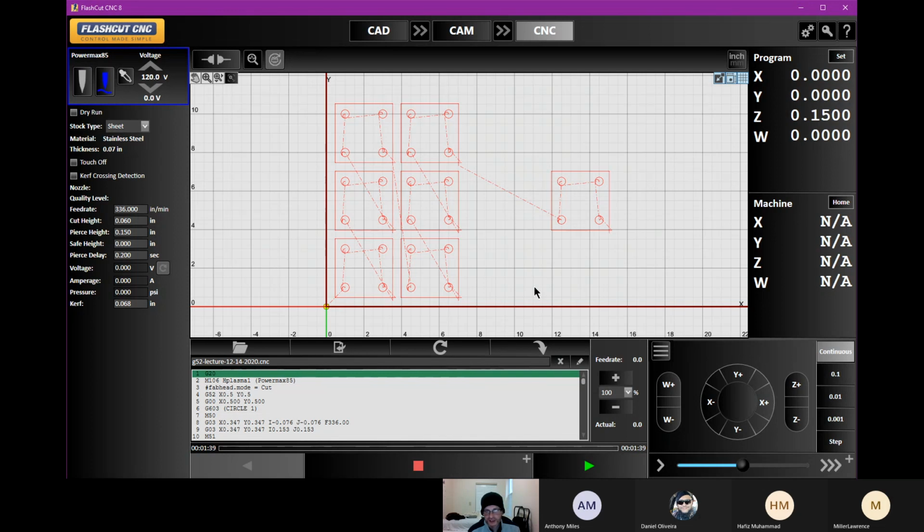We don't have to worry about adding that 1/2 inch or whatever. We can just start right at the home position. But G52 gives us the ability to move it where it needs to go. Okay. But like every other program, we do have to finish this out and bring it back to the home position. So I'm going to show you how to do that.